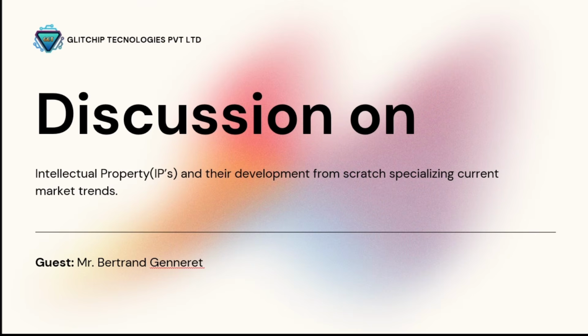And once you have it, you can start doing your RTL design. At this step, you will write the register transfer level code, which can be in Verilog or VHDL. And as you did your architecture specification, you're able to split the job between the different members of the design team. Each of them will code the RTL code of the different blocks. And of course, during this step, you will describe the behavior of your IP at the register level.